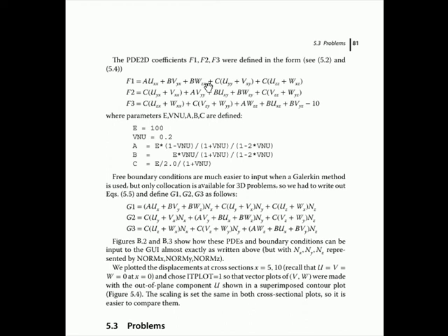So these will be the 3 partial differential equations. This is the derivative of sigma xx with respect to x. This is the derivative of sigma xy with respect to y, derivative of sigma xz with respect to z, and so forth. And the F is 0, 0, minus 10. So these 3 are all set to 0, and there are your partial differential equations.